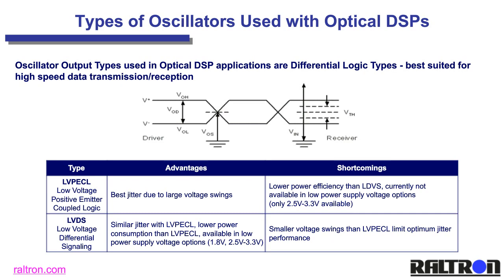Crystal oscillators go from 1 megahertz to maybe 200, 250 megahertz comfortably today. Clock oscillators, and then digital VCXOs, DCXOs can go higher in frequency, up to 1 gigahertz and more. So the frequencies we're talking about in this particular type of application are above 100 megahertz, and these in the crystal oscillator world are considered already high frequencies.